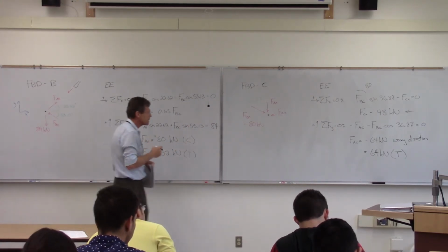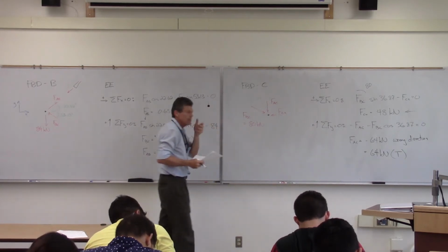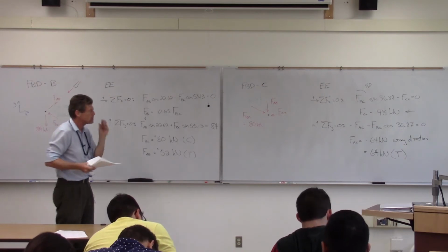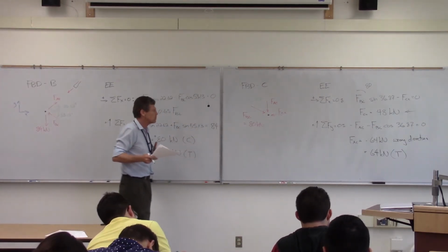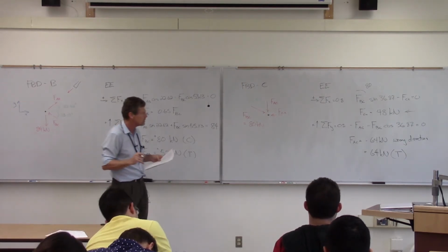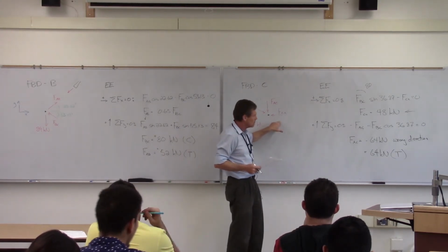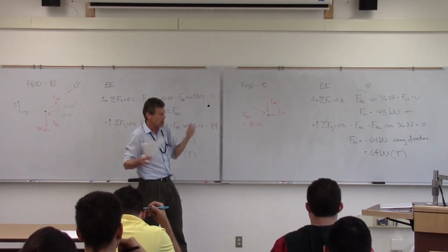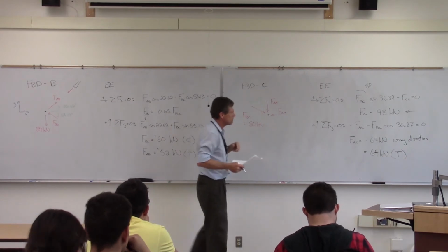What I realize then is that the sign will correct me. So don't worry about that. As a matter of fact, when we get into method of sections and when you go into structural analysis courses for you civils and stuff like that, what you're going to be doing is table methods, and we'll assume all tension is positive and all compression is negative, and it provides nice ways of calculating there. But this is just simply our two-dimensional equilibrium. We're assuming a direction, come out negative. The direction's fine, it's the sense that's wrong, so we just simply flip it over.